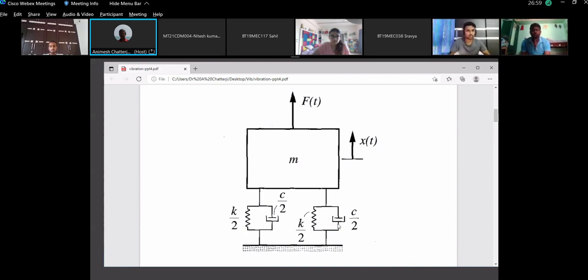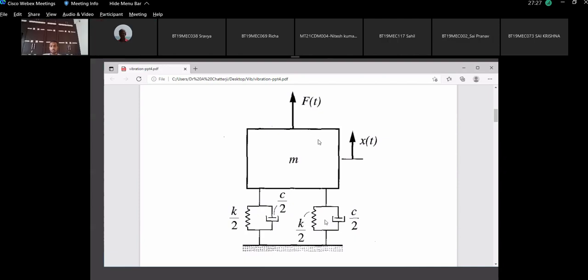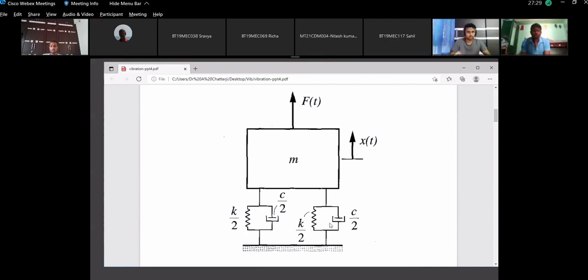So a rubber pad, we can call it an isolator because rubber can compress and provide stiffness. Rubber can also damp out energy. Even a helical spring we can call an isolator, but helical spring damping is very, very small. Its stiffness is very high, but damping is very small. But anything that possesses both stiffness and damping, we call an isolator.